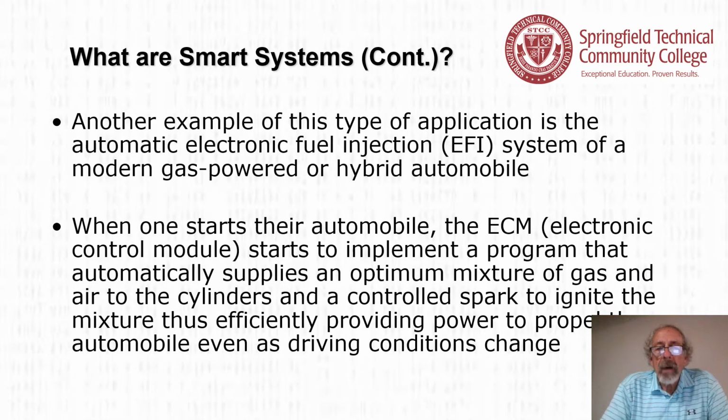Another example of this type of application is the automatic electronic fuel injection, or EFI system, of a modern gas-powered or hybrid automobile. Anything that is run by gas. When one starts their automobile, the ECM, which is the electronic control module, starts to implement a program that automatically supplies an optimum mixture of gas and air to the cylinders and a controlled spark to ignite the mixture, thus efficiently providing power to propel the automobile even as driving conditions change.